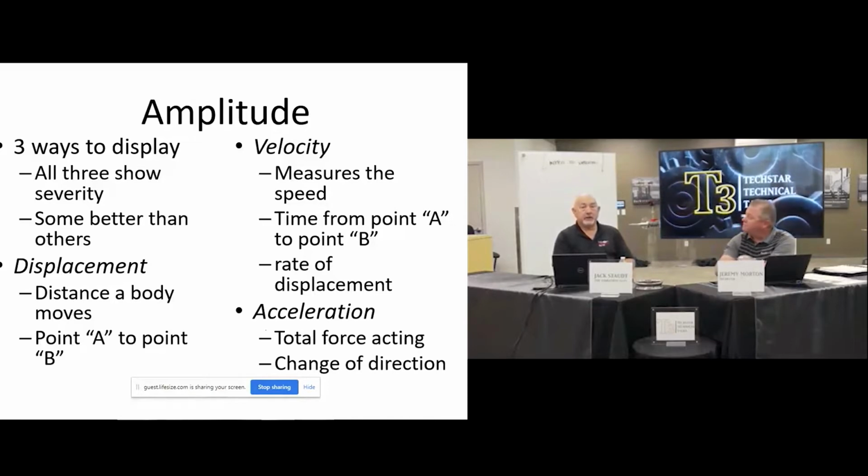I had a customer one time. He had his very cheap vibration meter mounted on his fan. About every 2 months, his fan would become unbalanced because of buildup on it. It was at an asphalt plant, and he would put a half bottle of water on top of the panel next to the fan, and when he would start seeing waves in the bottled water, he said it was time to call me to come out and field balance the fan. So that's what displacement is measuring, the top of the wave to the bottom of the wave. That was his 99-cent vibration analyzer.